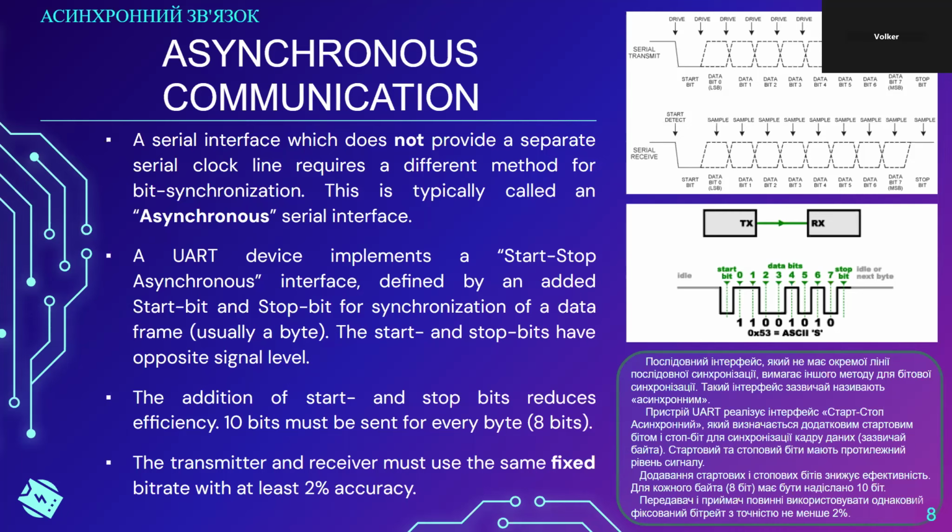Another issue here is that in order to get this 2% accuracy properly done, it is often required to implement a crystal oscillator in the microcontroller system. Most modern microcontrollers have fairly accurate RC oscillators on chip.